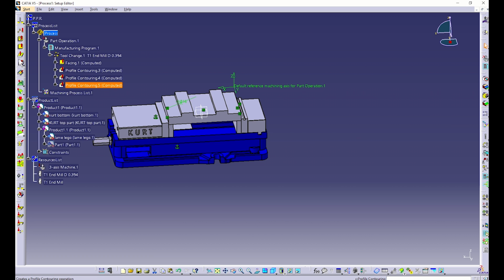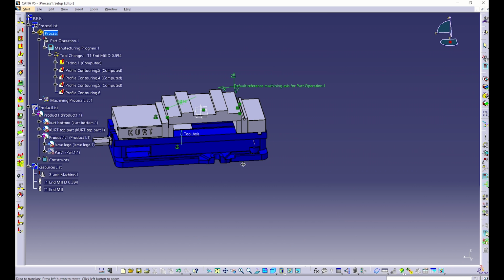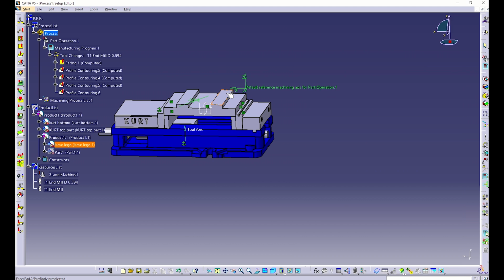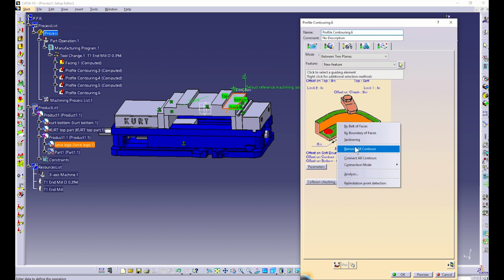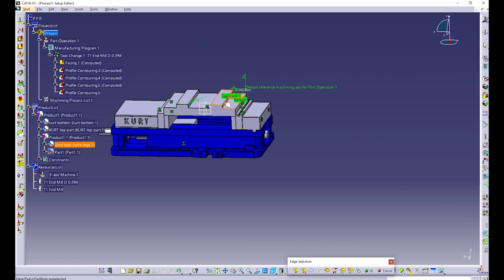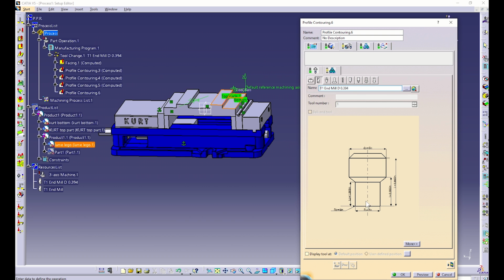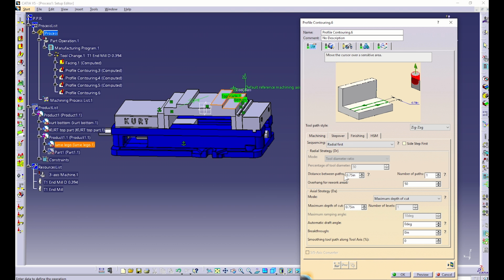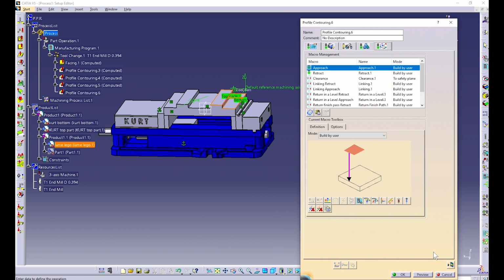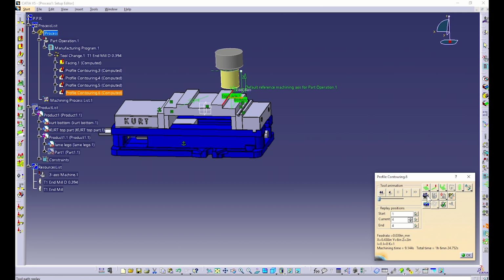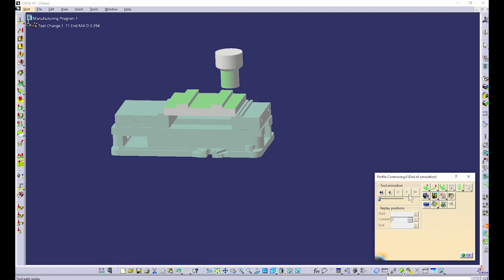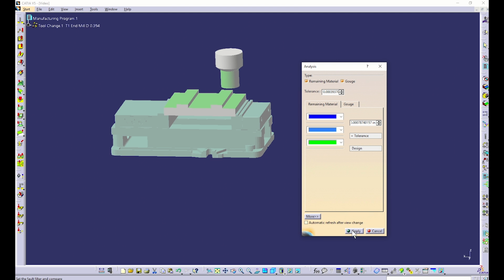But yeah, it's pretty nifty to be able to measure and see in advance, on the engineering side, before you actually get in there and start milling a part, and see how close it's getting to the vise. If you hadn't used these techniques, you would have been blindsided and in a lot of trouble. So if you're in doubt, throw in the vise that they provided you with the textbook and make sure you're not going to damage anything. Obviously this process is pretty easy with this Lego. Some parts will be a lot more complicated. You really have to take into consideration the vise and the bit itself so they're not breaking.